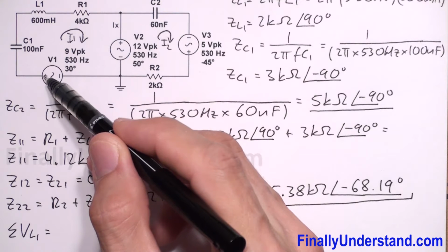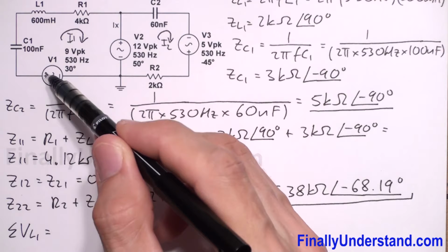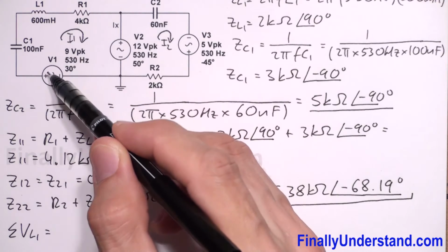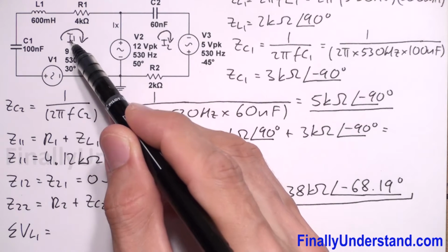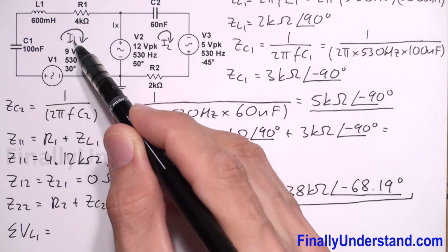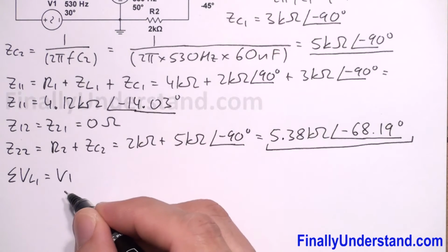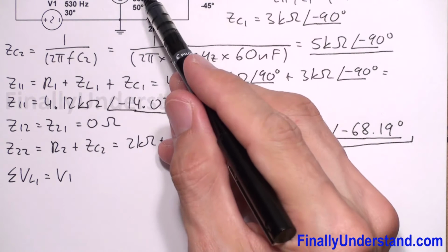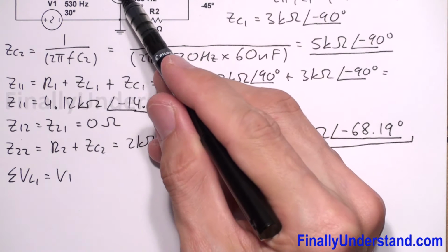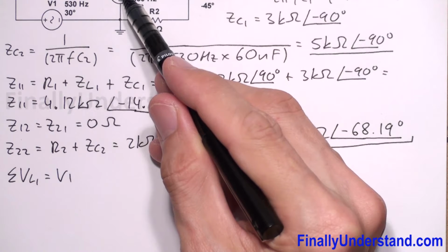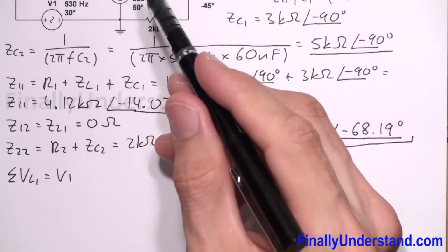If it is going to push in this way, I mean clockwise, this direction is going to match the direction of I1. That's why I'm going to say this is my positive V1. And V2 is going to push the current up, because I have a positive sign at the top.